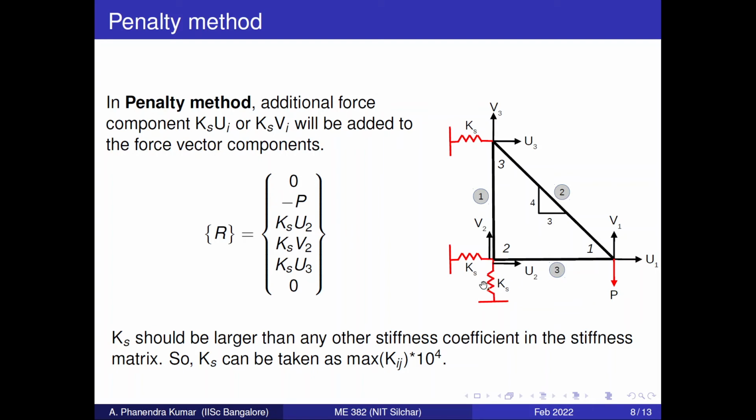As we have added a spring here, we don't have a support reaction now. Now we have a spring force. What will be the spring force? Ks into displacement. So Ks into V2. Here Ks into U2. Here Ks into U3.